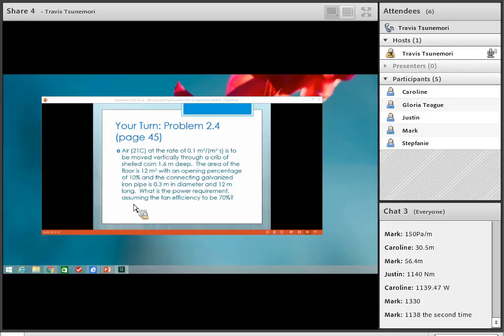This book uses a little m for wet basis and a big M for dry basis. The wet basis is the weight of the water divided by the weight of the water plus the weight of the dry matter. You can think of a biological material kind of like a sponge, and if we could take all the water out of it and have that really dry sponge, that's what the weight of the dry matter means.